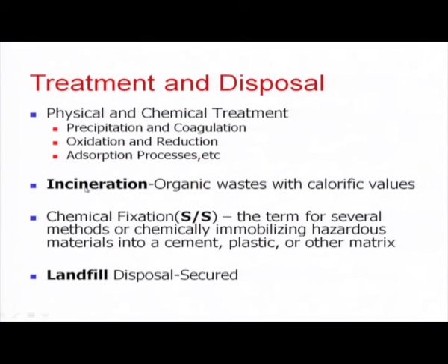And for the waste, there are two ways. The physical treatment should go to the landfill after checking. Otherwise, especially if it is organic waste and possesses calorific value, we can attempt to incinerate it, burn it, and it is possible to recover energy out of it also. And especially for inorganic based waste, chemical fixation, also popularly called stabilization solidification, is used to solidify and stabilize the waste so that it meets the requirement. Okay.